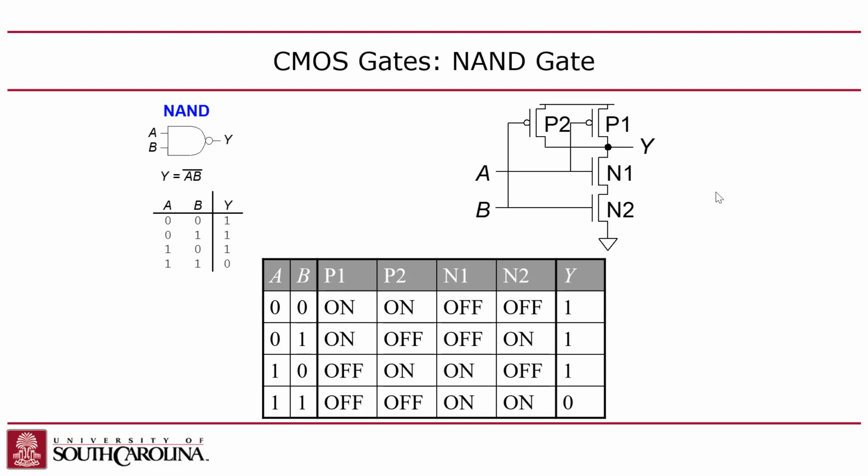which is why we see a NAND gate here, right? A NAND gate you can make. A NAND gate is just the opposite of an AND gate, right? So the way you do that is you put the two PMOSs in parallel, right? What that means is if they're in parallel, if either one of them is on, you're going to pull up. What does that mean? Well, remember, they turn on with 0. So if either input is a 0, pull it up.